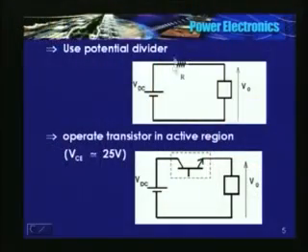So the moment I use a potential divider, which is nothing but a resistor, there is going to be a power loss, I square R loss. See here, this is the circuit. Input VDC, I have connected R, you vary this R such that you get the required output voltage.